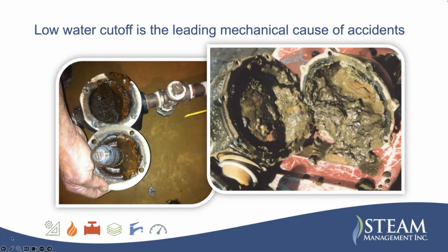And the owner says, "Oh, we blow that down every week." Well, you could see all the crap up in there. There was no way they blew this down. And the one on the right, a friend of mine sent to me, this was a low water cutoff, and you could see it was filled with sludge and mud. There was no way it was going to operate up and down.